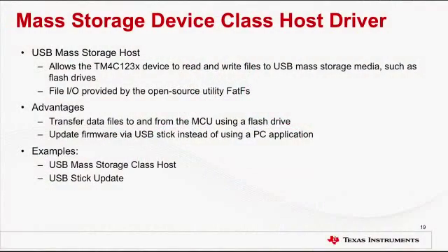There are several example applications in Tiva C series that can be good starting points for supporting other HID devices. The USB mass storage device class allows an application to act as a physical storage device for use by other USB applications or for a host operating system. Because the type of storage can vary by application, the mass storage class abstracts the storage within a set of block-based APIs that are provided by the application to the USB library.